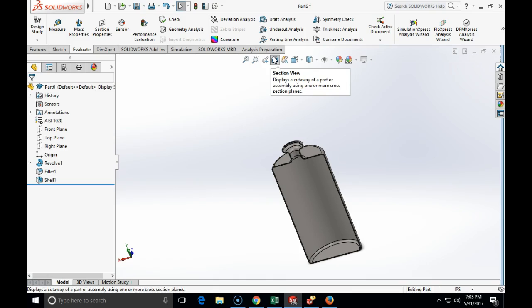And if we try to build something that is hollow, and it doesn't matter if it is with a uniform thickness or with a semi-uniform thickness where you have discrete areas with different thicknesses, instead of messing up with very complex sketches, the most convenient and the most robust model, the model which will be easiest to modify, will be to use the shell command.